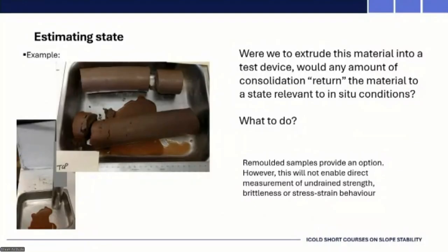Okay. Clearly, it's not in the same state it was, for all the reasons already mentioned. There's some free water that's separated out. During the penetration, you've perhaps compressed it and released water, maybe during the transport, whatever. Now, how do we do something meaningful with a sample that looks like that? You can remold it. Remolding, I mean, you can reconstitute it in the laboratory using one of the methods Louis mentioned, moist tamping, slurry deposition, perhaps, but what is your target void ratio?